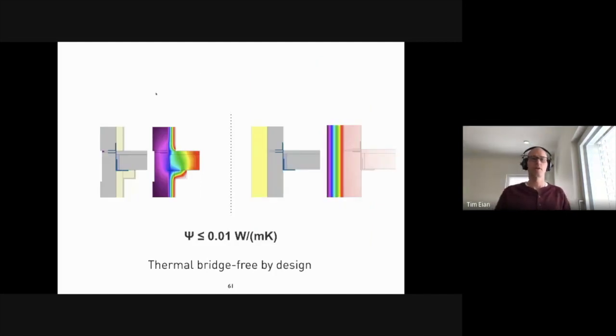These are just some simulations and photos of where you can see how something makes a difference. On the left-hand side, in this picture, I show a tip-up concrete building that is insulated on the interior with a floor slab that attaches to the tipped-up concrete wall. That, by the way, came from a LEED certified student housing project we worked on. We consulted on making it better. So that's the standard condition, and you can see there's some pretty massive thermal bridging.